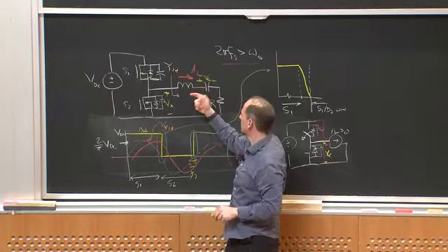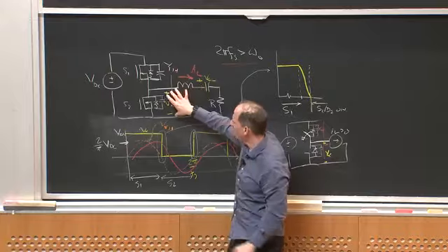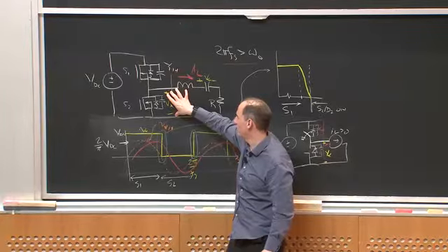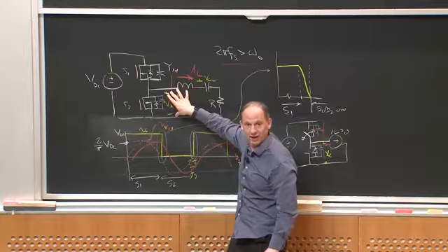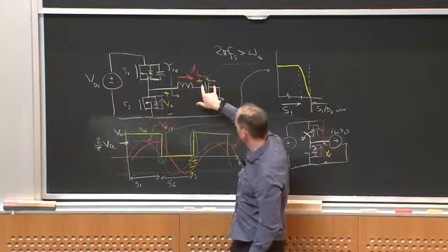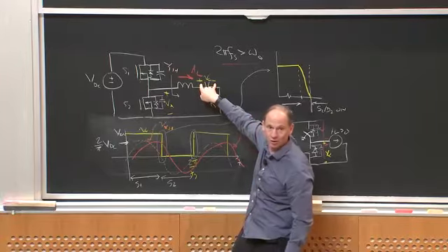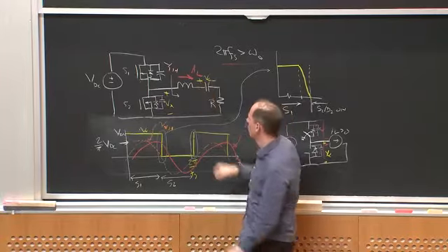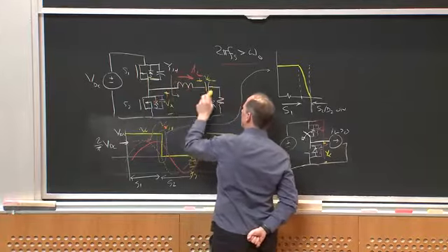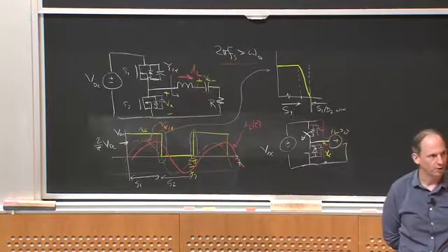And in fact, if you remember, we said that the capacitor voltage in a series resonant network can be Q, the Q of omega naught, times the fundamental input voltage. So if I have a Q of 10, then whatever the fundamental of this voltage is, if I ran at resonance, VC would be 10x that. Or if Q is 100, it would be 100x that. So you've got to be careful. The device voltages are nicely limited, but these two components can have pretty big voltages on them, depending upon the quality factor of the network.